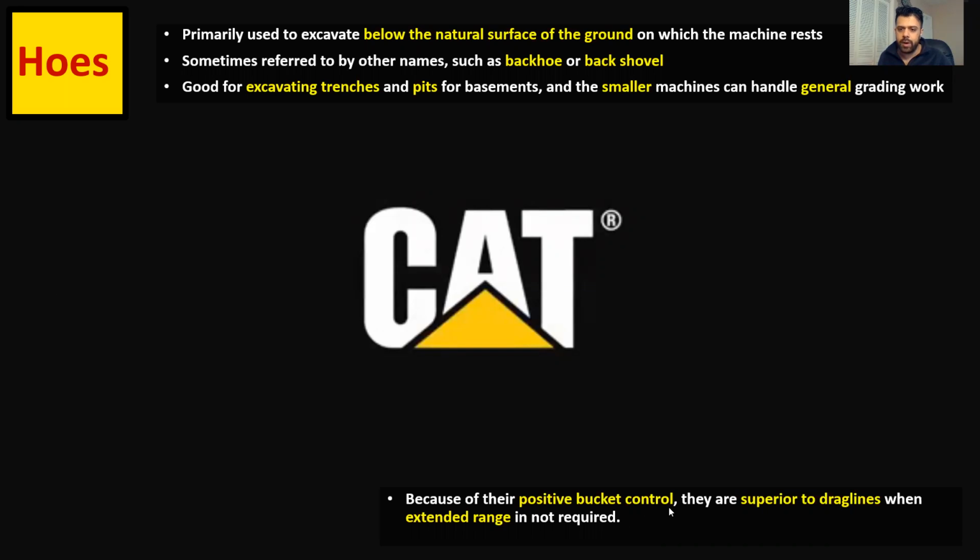Because of the positive bucket control, they are superior to draglines when the extended range is not required. The main purpose of using draglines is when you need an extended range. So if extended range is required, a dragline is obviously the first choice.